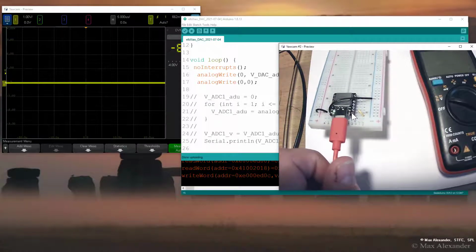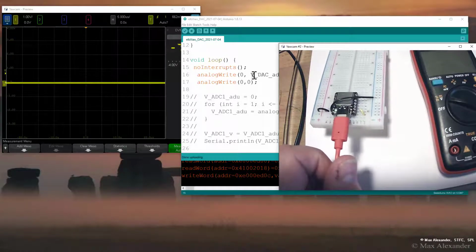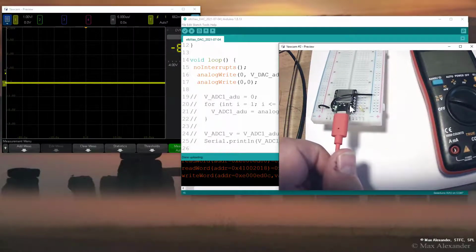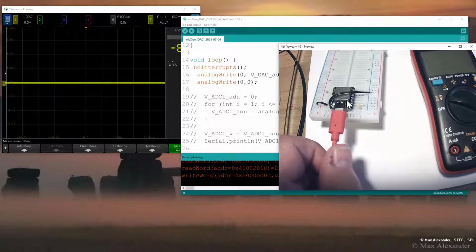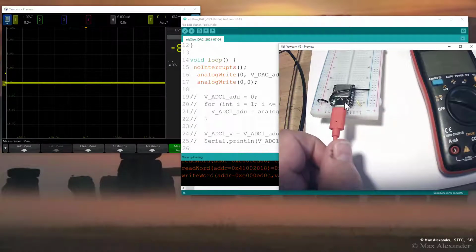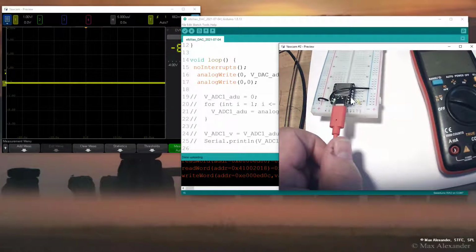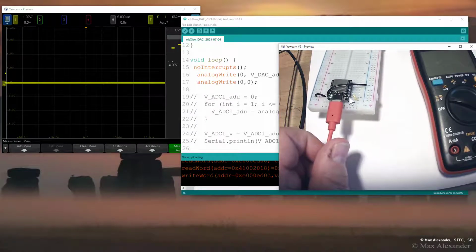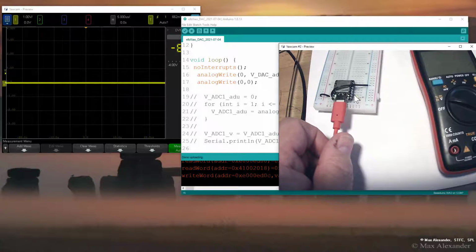default, turn off the code I'm running, which has the no interrupts in it, and set it up so the interrupts are working again. The first time I click it, it does a reset and says, okay, start the program over again. And then if I can do it a second time within about half a second or so, then it'll say, okay, 2 resets in a short period of time, go back to bootload case, factory default, and now it's ready to run all over again.